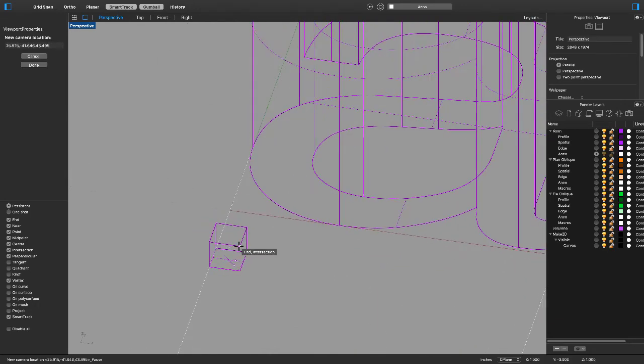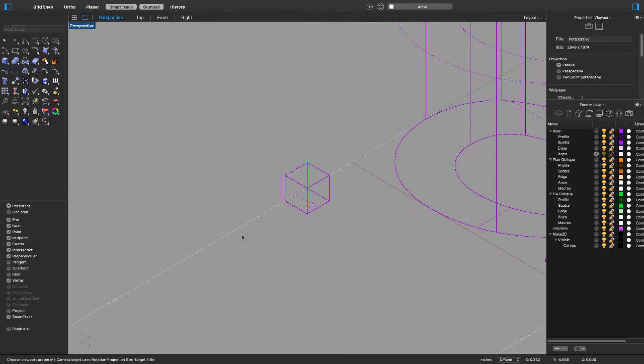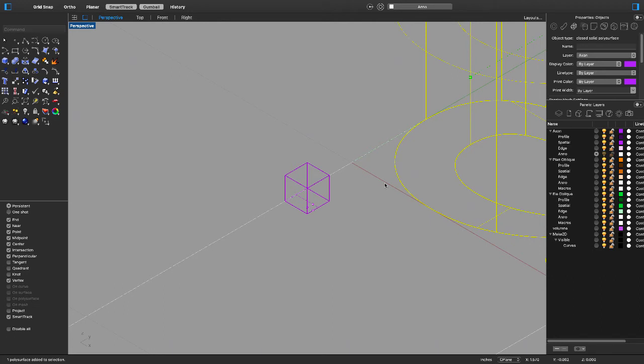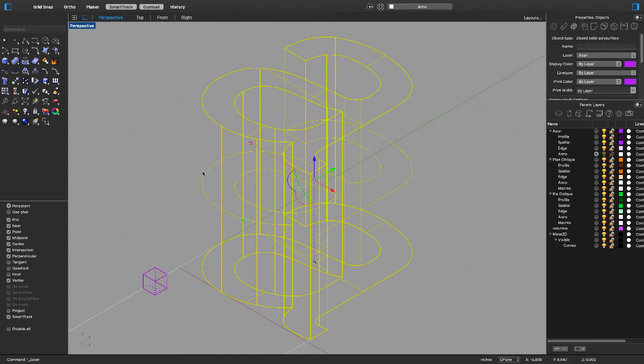The first click will place the camera, and the second click will place the target. Anywhere along this line will give you a dimetric view, as well as along this line here. If I was to click on this rear point, I would have an isometric view. Once you're in a view, it is important that you do not orbit or pan in and out, but rather use the zoom selected command before you make 2D.